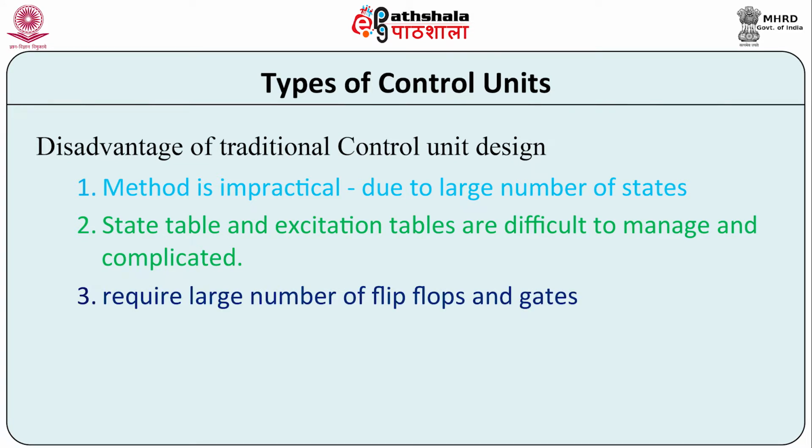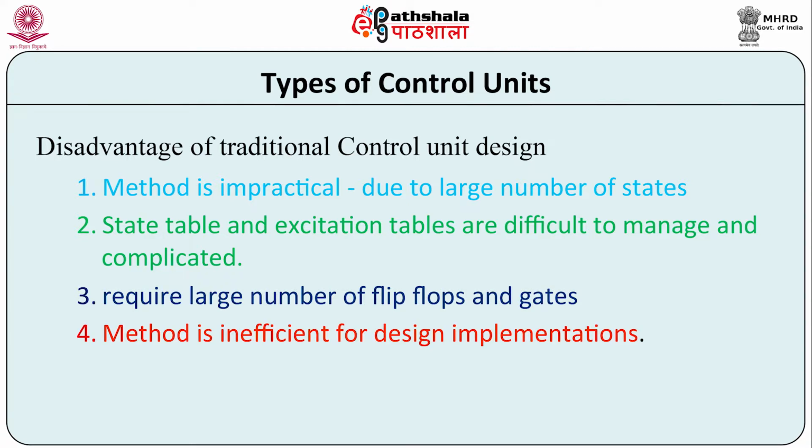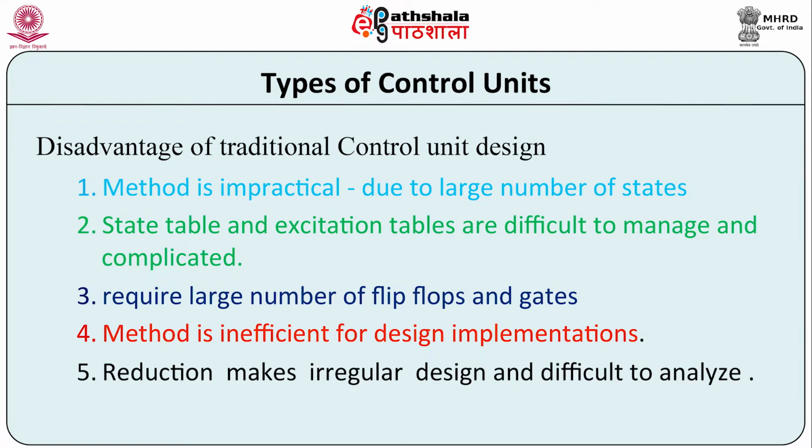Third, control circuits based on this method require large number of flip-flops and gates, indicating use of only SSIs. Fourth, the number of connections based on SSI circuit are more. Hence, this method is inefficient for design implementations. Fifth, if the number of circuits are reduced, then design becomes irregular and difficult to analyze later. Last, troubleshooting is also difficult.